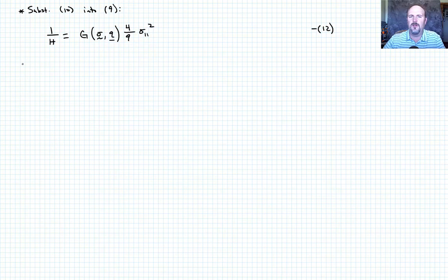Now let me give you a little note here. We've assumed in this case that the material is isotropic and that our yield surface expands isotropically, that is, without respect to where we are on the stress curve, really only as a matter of a radius along a particular axis.